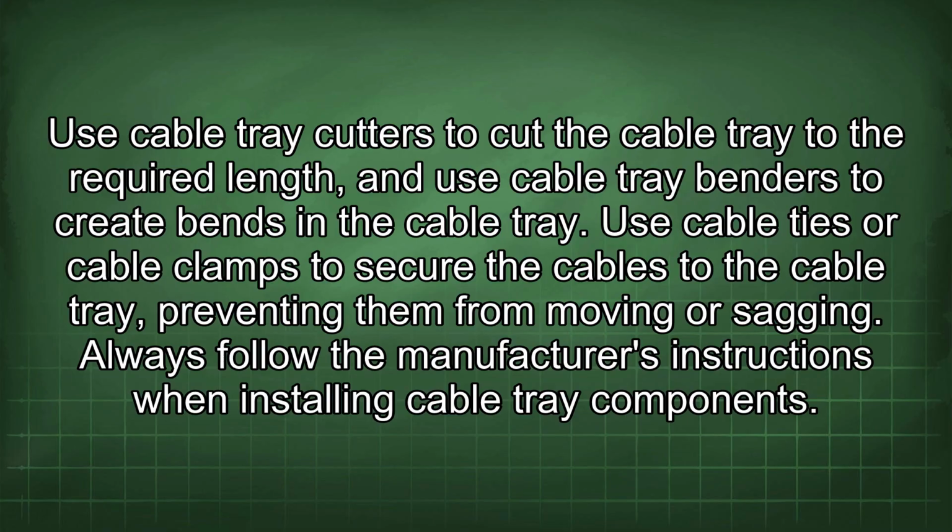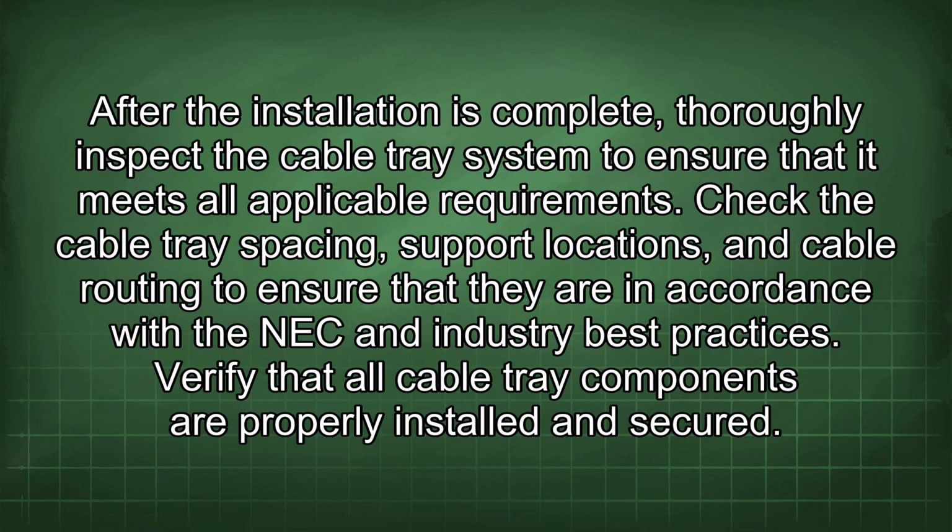Use cable ties or cable clamps to secure the cables to the cable tray, preventing them from moving or sagging. Always follow the manufacturer's instructions when installing cable tray components. After the installation is complete, thoroughly inspect the cable tray system to ensure that it meets all applicable requirements.